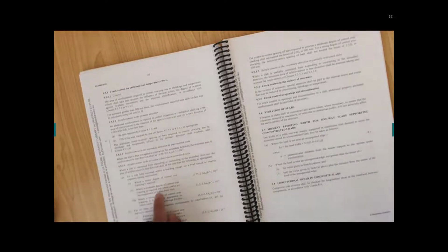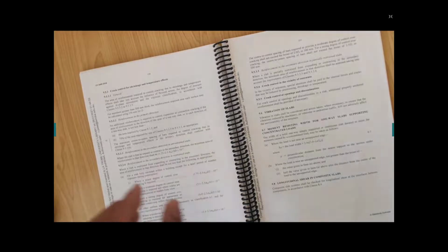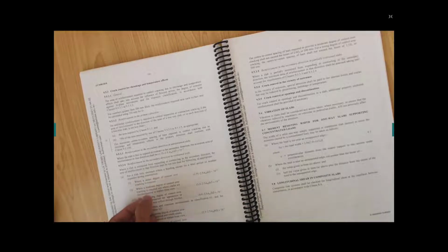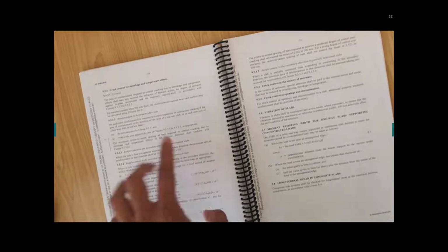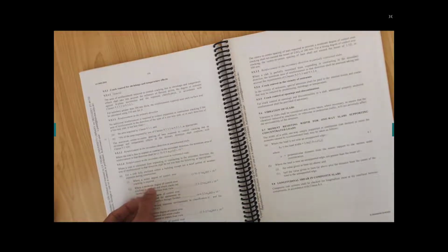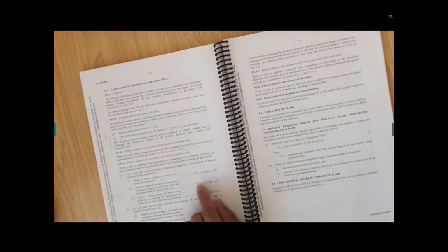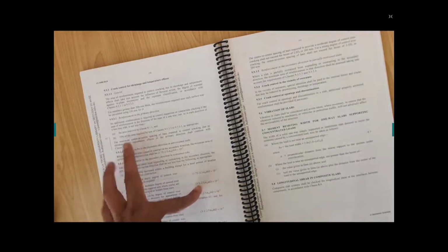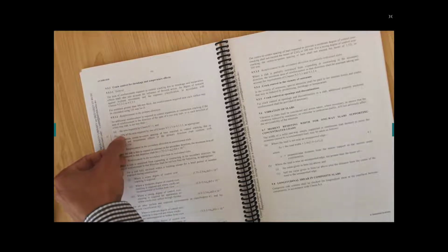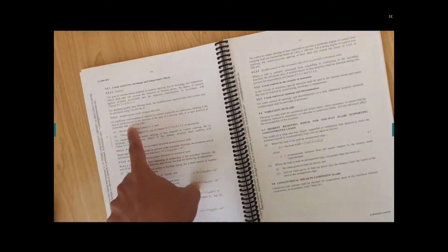If you don't know, you can assume that. And let's say this slab is sitting in an enclosed environment, with classifications depending on where the slabs are sitting. Let's say a moderate degree of control. We don't want to go for the minor one; let's do the middle one, moderate degree of control. So we make two assumptions. First, restrained slabs, and then a moderate degree of control. In that case you can just take these equations as the Ast minimum for crack control. And by the way, don't forget to multiply by 75% when you're designing for the primary direction.